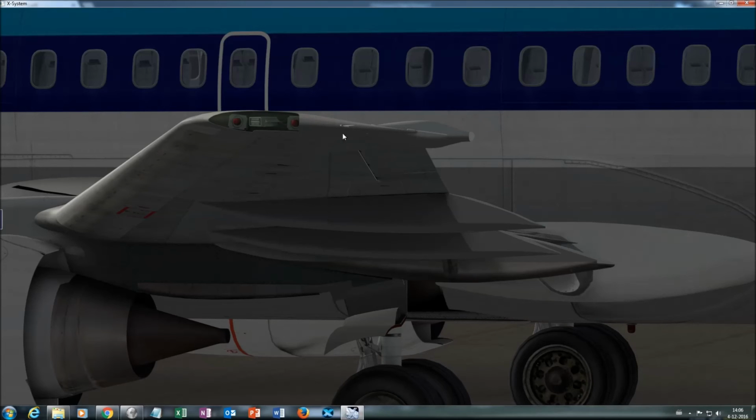And because it is curved on top, it causes the air that flows over the wing to flow faster than the air that flows beneath the wing. If the speed of the air above the wing is faster, it means that the pressure on top of the wing is lower. So you get a pressure difference. The pressure of the air below the wing is high, while the pressure on top of the wing is low.